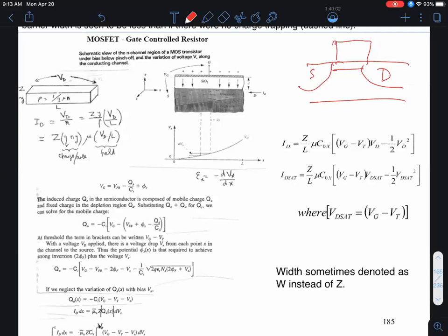Yes, very good question. In fact, in outer space, things are even worse because the chips are going to be subjected to high energy cosmic rays, okay? On the Earth also we have cosmic rays, but thankfully the atmosphere blocks out 99.9% of the cosmic rays, okay? Cosmic rays are high energy particles like alpha particles and gamma rays and things like that, all of which can cause such charge trapping in ICs and therefore can cause them to fail. So it's a huge problem that NASA faces.